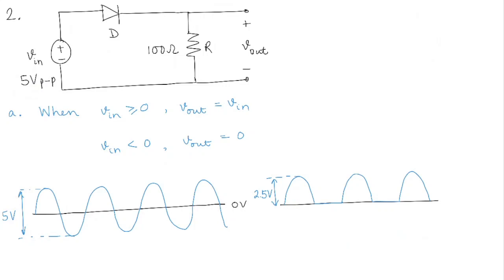the current that is flowing through the diode, how does that flow in the circuit? It comes from this signal source, right? It flows like this, and then it flows through the diode and it flows into the resistance. It cannot flow in the output because it's just an open circuit here. So it has to flow through this resistance and back. So the current is flowing in this loop.